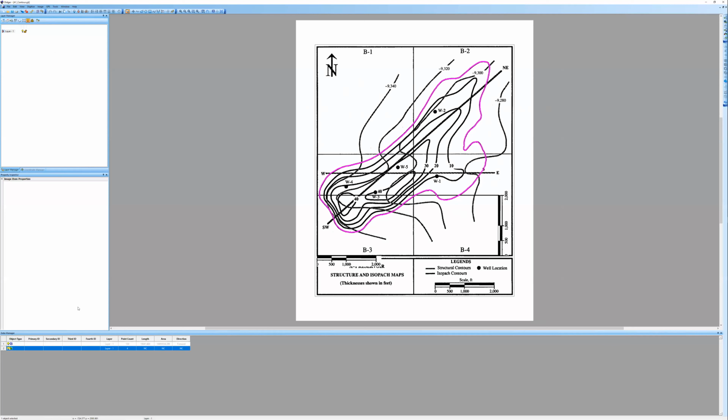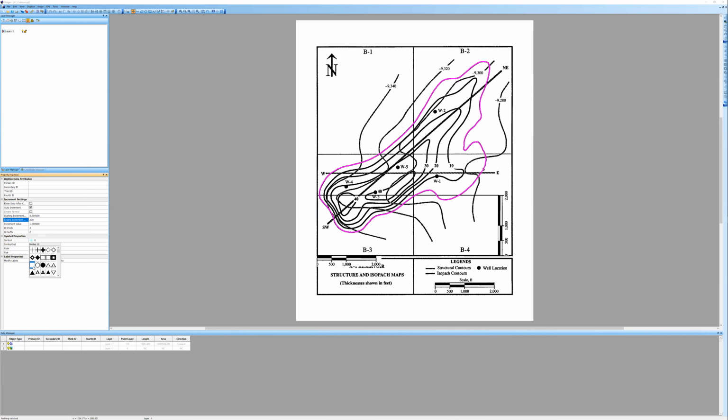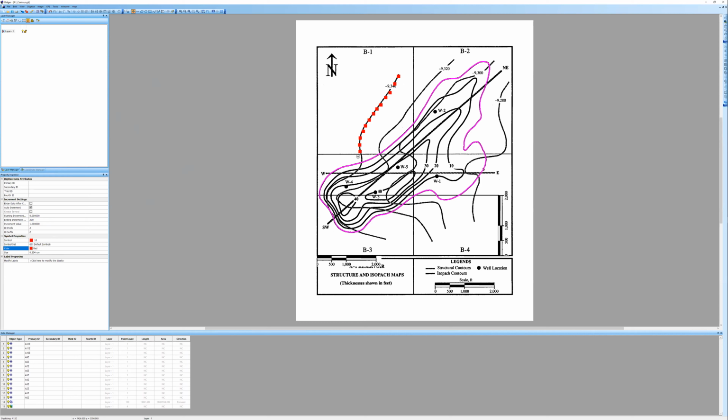And then you can make a lot of things here. For example, let me show you how you can digitize points. Very simple. You go here, auto increment. I put the incrementation, let's say the limit to up to 200. Okay. I take a sign which I would like to use, and I switch to red. And then I can make here digitization, right? You can see here I can select points, and this is the way how it goes. You can select polygons, whatever. So once again, it's a very useful and very flexible software, and this is really easy to use.